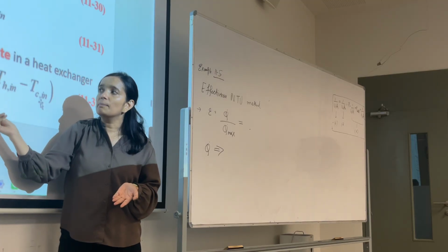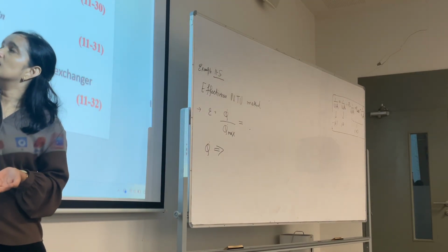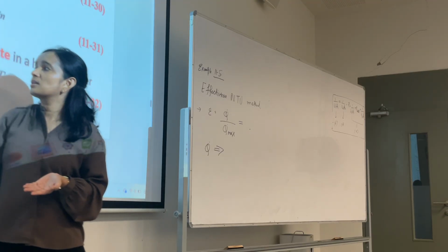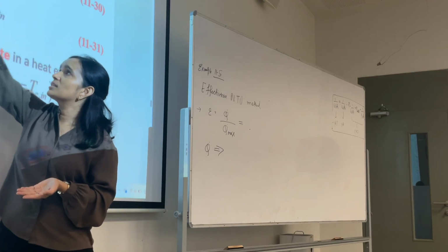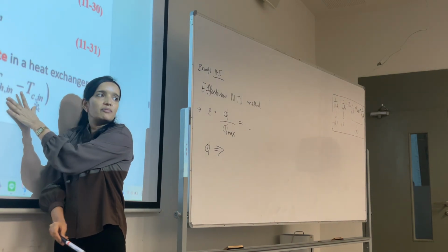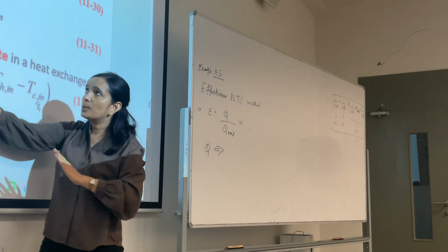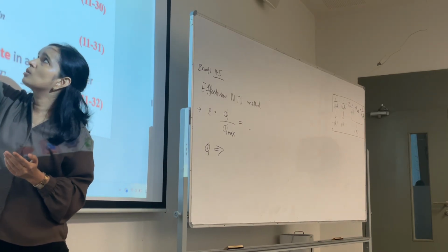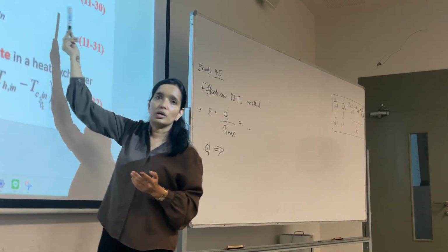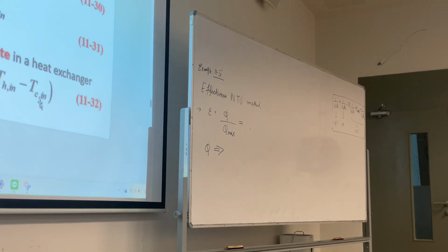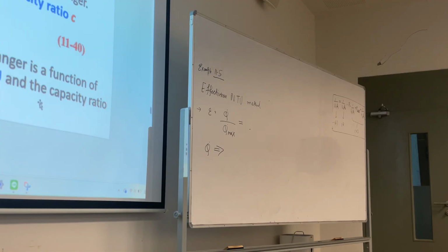This you will use minimum. If this is smaller than the hot water, you will use this here. And this is smaller than the cold water, you will use this here. And this will be the maximum difference. Okay. Whereas this will be, if you are calculating for cold water, cold out, cold in, hot water, hot in, hot out. Okay. So this is your heat transfer effectiveness.